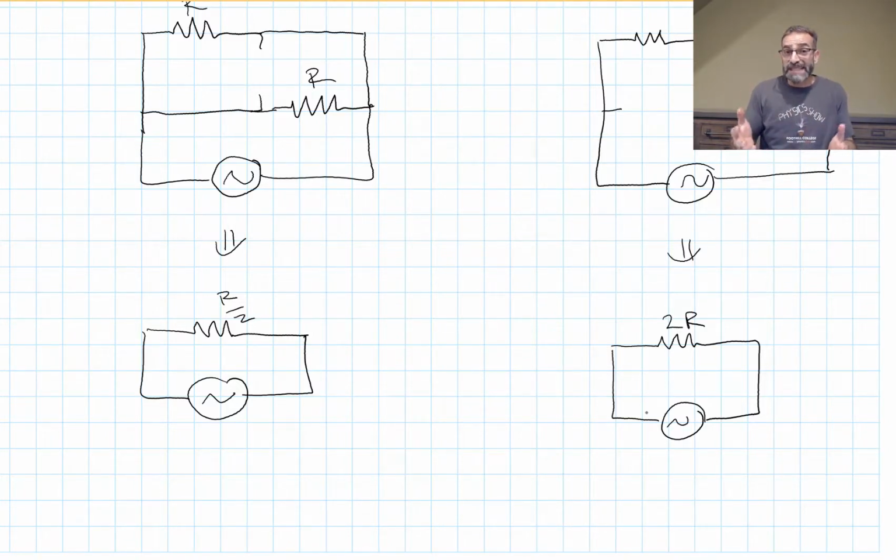A simple example would be if you have your power lines in your house, they run at a very low frequency, 60 hertz. The power cycles 60 times every second. But audio and video signals have much higher frequencies. And if you have those wires running right next to your electrical lines in your walls, they might pick up some noise. So you could run your audio signal through a high pass filter that would look like a very high resistance to that 60 hertz. It would not allow that to pass through, but it would allow your high frequency audio and video signals to pass through no problem.